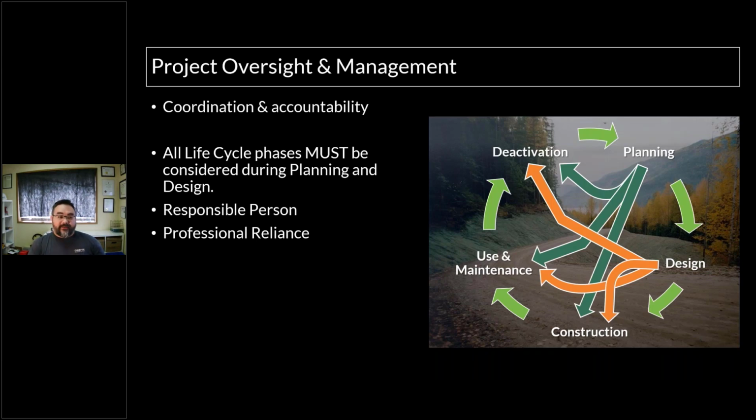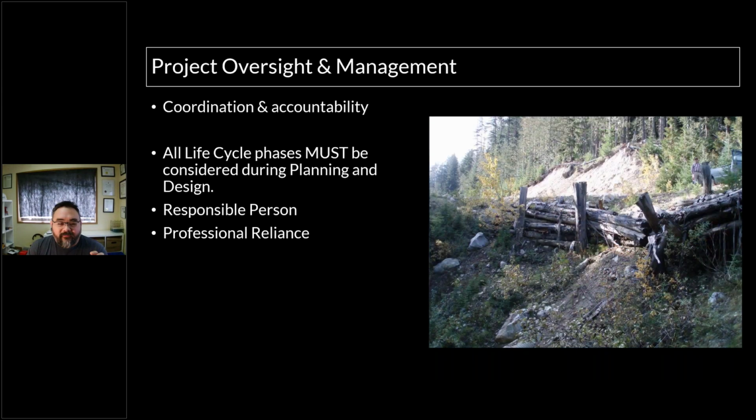And for example, if you have a temporary road, you may build that, or you will build that road differently than if it was permanent. And you may have things like temporary fill retainment structures, so you don't have to either reach down the hillside and get that fill later, or you don't have to end haul material away.